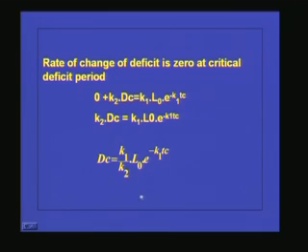of this Streeter-Phillips equation, because they have considered only one discharge point for the waste. But we know that if you take a stream, it will have many point sources of wastewater coming to the system. So we have to make the oxygen sag curve for each discharge point and superimpose them. Then only will we get the actual oxygen sag curve.